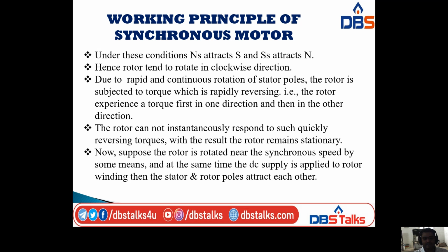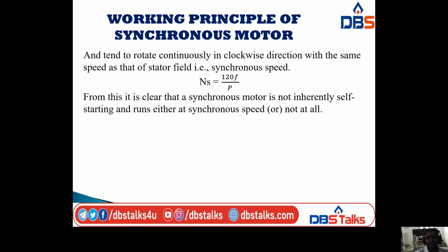So there is attraction, and that's why they tend to rotate continuously in clockwise direction, at the same speed as that of the stator, that is synchronous speed. You know already the formula of synchronous speed, that is N_s is equal to 120 f by P. From this it is clear that a synchronous motor is not inherently self-starting, and runs either at synchronous speed or not at all.